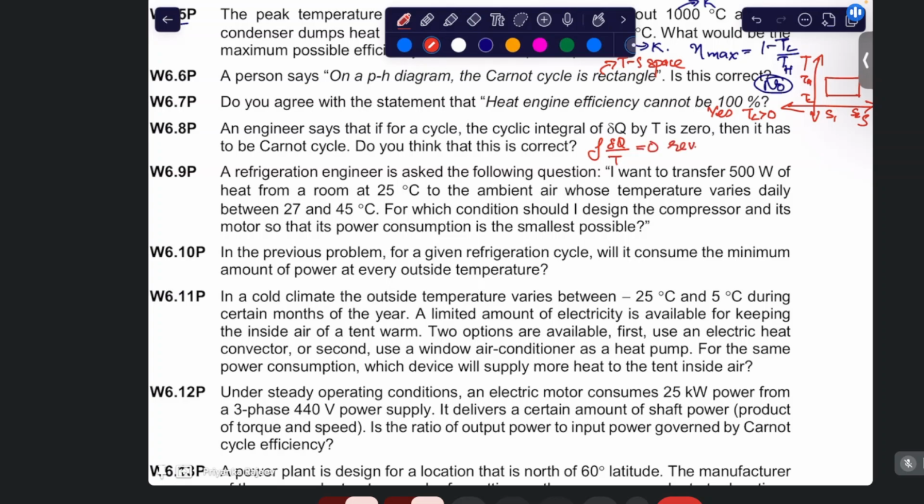That is for a reversible process. We can have any kind of fully reversible cycle that exchanges heat at more than 2 temperatures. But a cycle with exactly 2 heat exchange temperatures is indeed a Carnot cycle. A general reversible cycle might have a different shape, right?